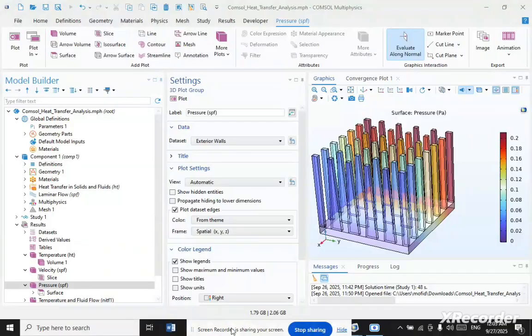Two important parameters are always kept in mind while designing any new micropin heatsink. Firstly, the fluid flow should be uniformly distributed throughout the heatsink. Secondly, there should be no local hotspot generation in the bottom wall of the heatsink, with uniform substrate temperature.